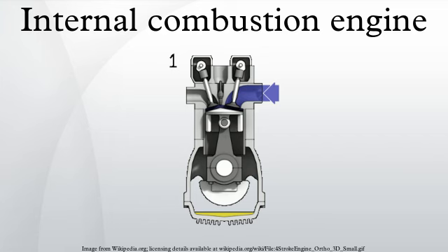Diesel ignition process. Diesel engines and HCCI engines rely solely on heat and pressure created by the engine in its compression process for ignition. The compression level that occurs is usually twice or more than a gasoline engine. Diesel engines take in air only, and shortly before peak compression, spray a small quantity of diesel fuel into the cylinder via a fuel injector that allows the fuel to instantly ignite.